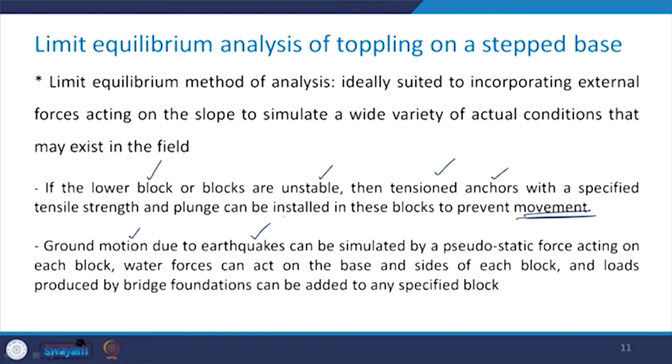Then water forces can also act on the base and the side of each block, and the loads which are produced by bridge foundations can also be added to any specified blocks. So, in this particular manner, this limit equilibrium method of analysis can take care of many such external factors which are more relevant in the field. But we will first learn about the basics behind this limit equilibrium method of analysis in case of the slopes experiencing toppling kind of failure.